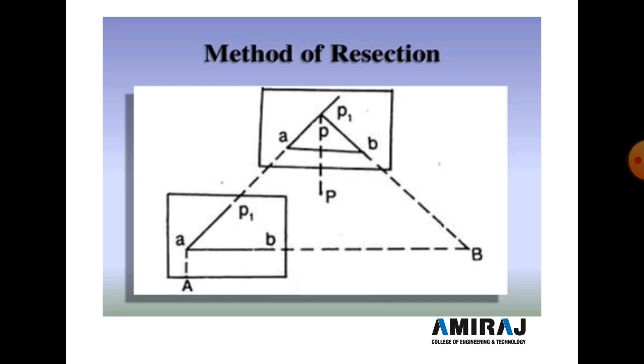Now the plane table is set up at A and perfectly leveled. Then centering and orientation are done at station A, bisecting the ranging rod fixed at point B. The plane table is clamped, and the line AB is already drawn. With the help of the alidade, touch the point a, bisect the ranging rod fixed at P, and draw the line as an imaginary line.